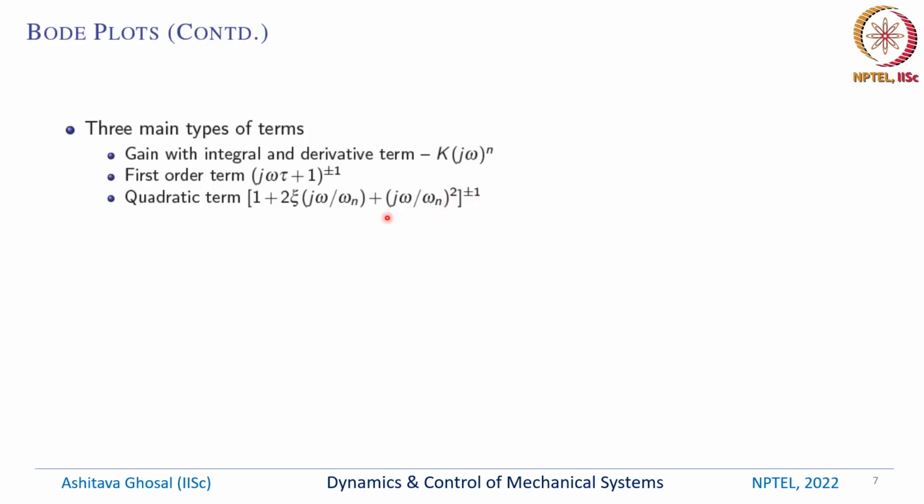So it is very similar to omega n squared divided by s squared plus 2 psi omega n s plus omega n squared. So remember, in root locus we could see that there were these quadratic terms, and again s is substituted by j omega, and we can rewrite those quadratic terms in this form, either in the numerator or in the denominator.